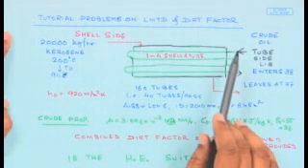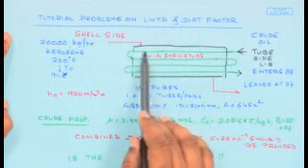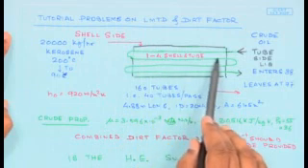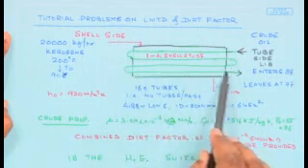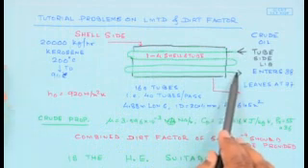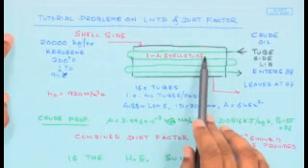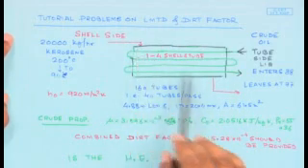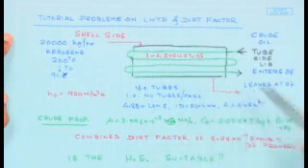It is a 1-4 heat exchanger. So, the tube side fluid enters, completes the second pass, this is the third pass, and then comes out after it crosses the shell 4 times. That is why it's the 1-4 shell and tube heat exchanger, that means 1 shell pass and 4 tube passes.